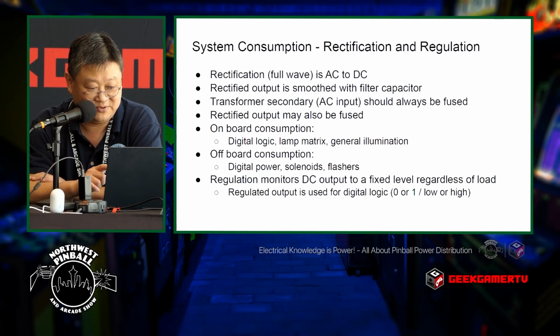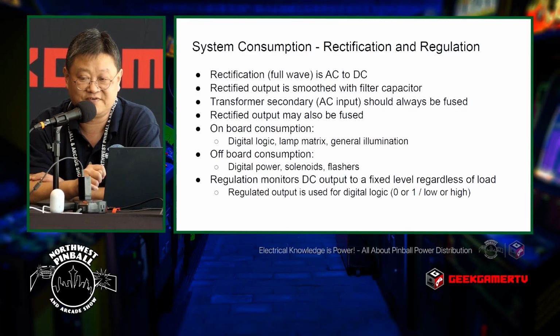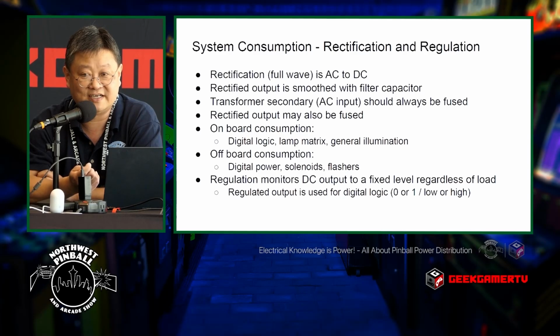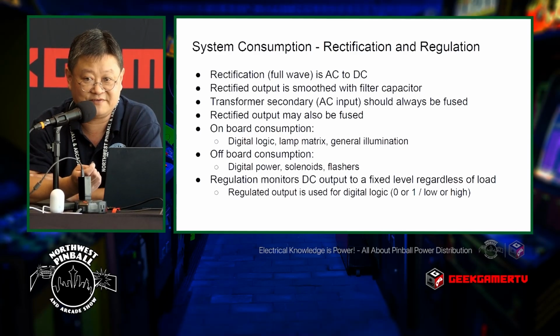And this final point here is about what I mentioned earlier about regulation. Regulation is used to provide a fixed voltage output level. So if I provide a regulator with 10 volts and its job is to regulate output at 5 volts, it will throw away half of that voltage. 10 volts, I don't need those 5 volts. I'm going to throw them out and I'm going to give you 5 volts based on the load that I have. Maybe, for argument's sake, the load of 1 amp.